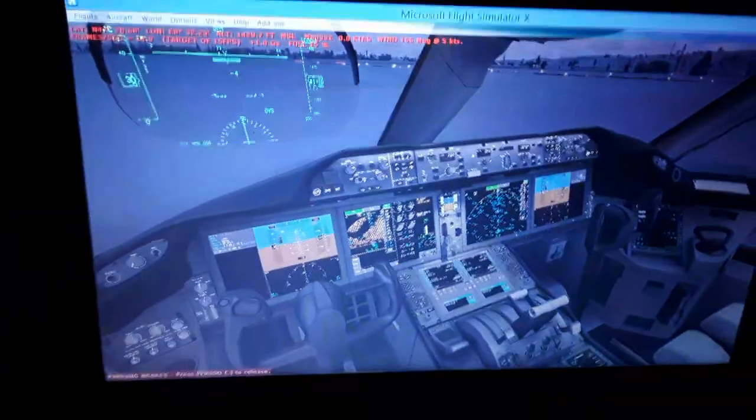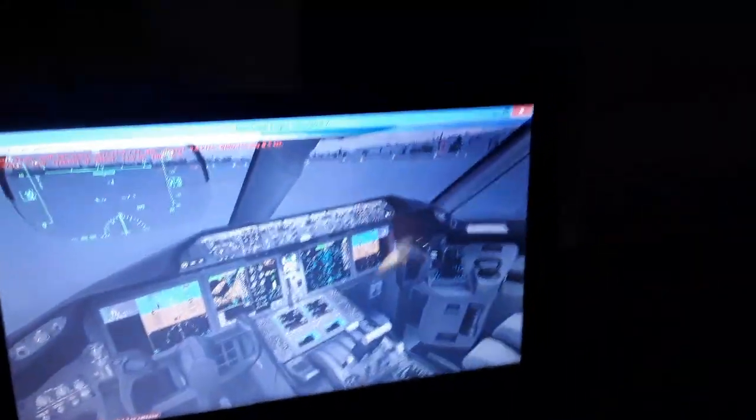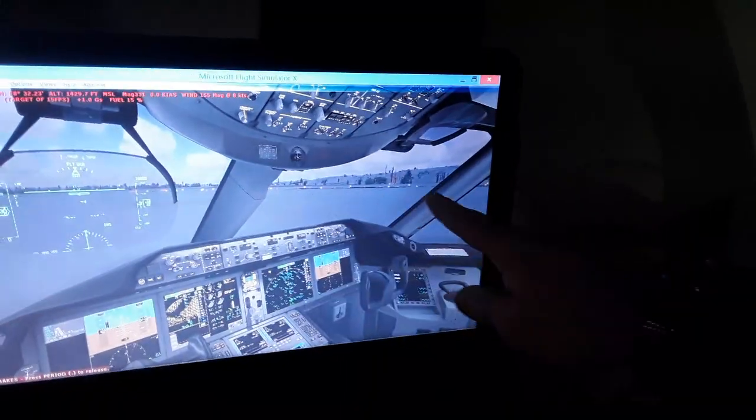The flaps: we're going to use 15 degrees of flaps for takeoff. We're going to use 4.25 degrees of horizontal tail trim stabilizer for takeoff. Also the takeoff speed; we're going to select the runway. You can see the runway here, runway 14 at Zurich International Airport. The runway length, the runway slope, the wind direction and speed, the barometric pressure, the density of the air. We're going to use full takeoff thrust of 99 to 100%, 15 degrees of flaps, and 9 degrees of pitch attitude at rotation in flight.